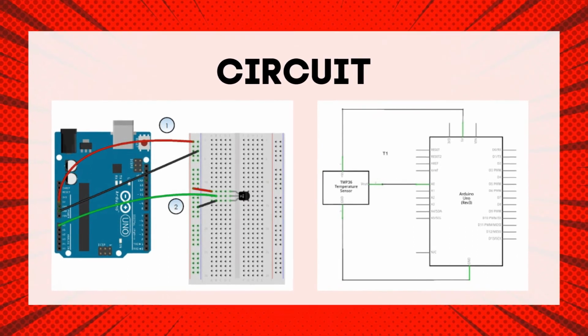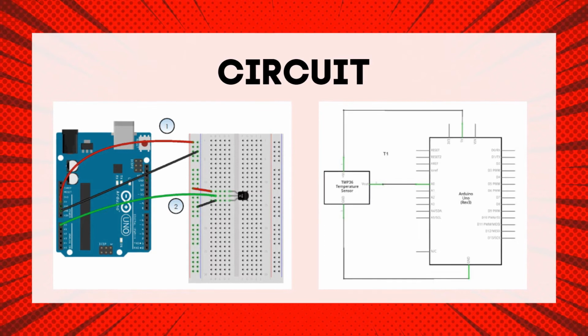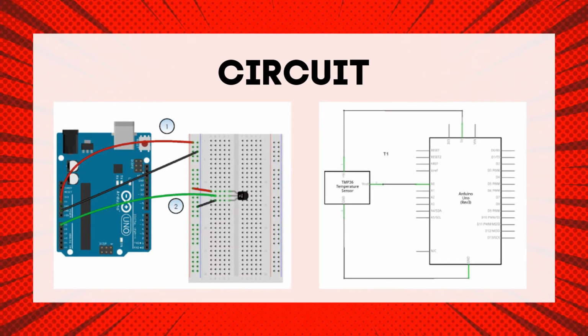Again, the temperature sensor that we are going to use is a TMP36 semiconductor sensor type, which is a low voltage, analog precision centigrade temperature sensor. Unlike the photoresistors or the LDR, these sensors don't act like a resistor. Therefore, the only way to read the temperature value from the sensor is by plugging the output pin directly into the analog pin.